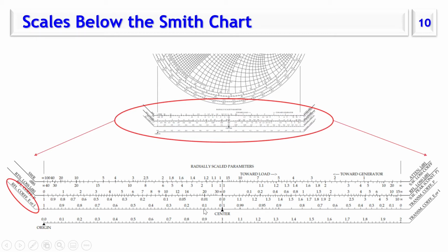They are two different things. We are working on the reflection coefficient for the electric field or the voltage. We can also find the reflection coefficient in terms of dB, the return loss, from the horizontal scale, and everything is relative depending on the size of the Smith chart. So everything is sort of calibrated.